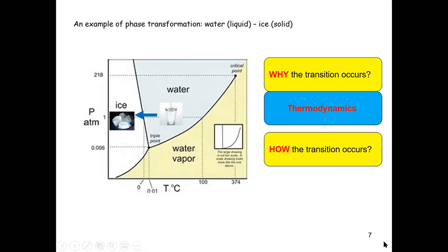Okay, so that basically answers the question of how the transformation occurs. The transformation occurs through nucleation and growth, right? The nucleation occurs through fluctuations, because there are always small nuclei in the system, even in the liquid state. But if you cool the system below the freezing point, they begin to grow because these small nuclei become thermodynamically stable. Then more and more atoms add onto the nucleus.